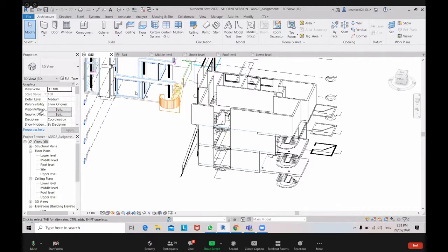And then there is the top constraint. It should not be what it is, it should be unconnected. You can select it here. Okay, there is unconnected. And then you can change the number here. Since it's unconnected, you can make it, for example, 1 meter. Click apply. See, it has become small.